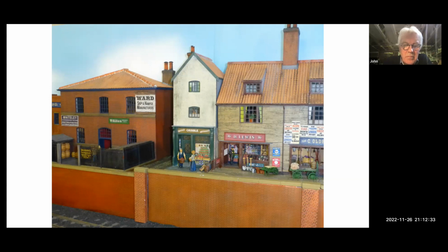If you move the material higher up that taper, you will get a wider beam, and a wider cut. And if you move it below the focusing point, the beam will open up again. It'll come down to a point, and then it'll start to get bigger again. So again, you'll get a wider cut.